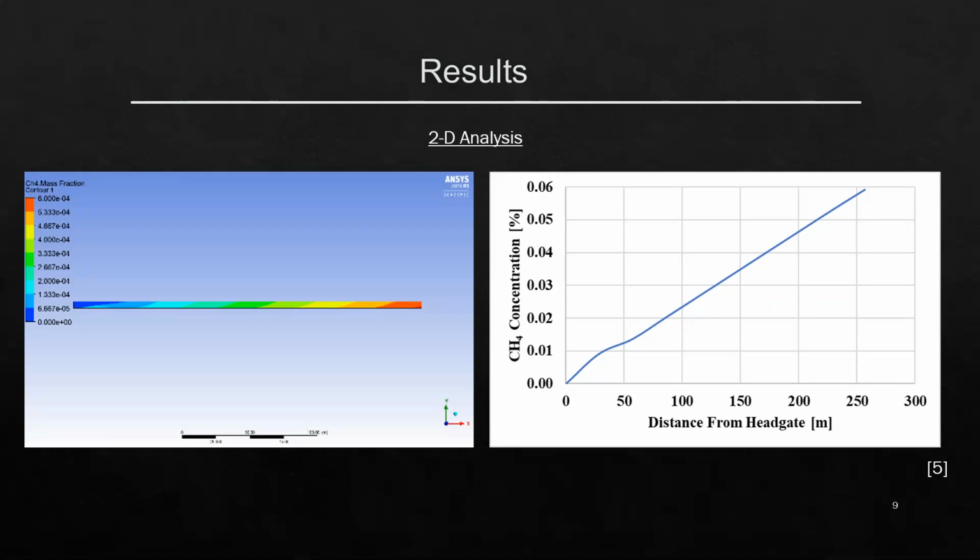So could you please describe a little bit about your simulation? What is the resolution? What is the grid size? What kind of model do you use? Anything you remember? Yeah, so I don't have it pulled up right now. For the grid size, I did do a bit of a study. I simply used the number of divisions. I put a face mesh over this, and then I worked down the divisions until my results came out very similar.